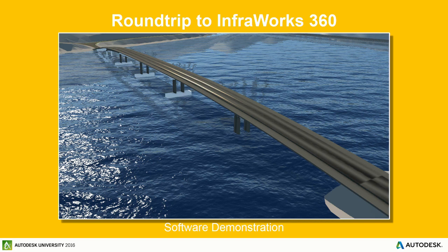Well, within InfraWorks, it's kind of an automatic thing. Now, if you're using Civil 3D, for example, to do that, that's a bit more accurate. And again, you can use, for example, Dynamo to pull that data out, and then from there, bring it into Revit and keep, for example, the profiles perpendicular to the alignment, things like that.